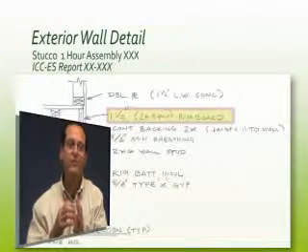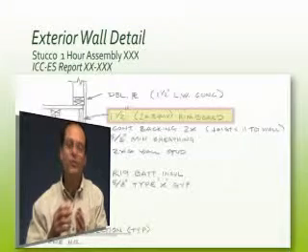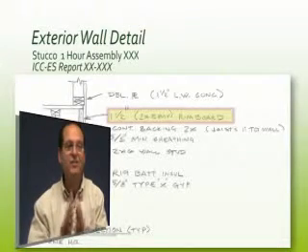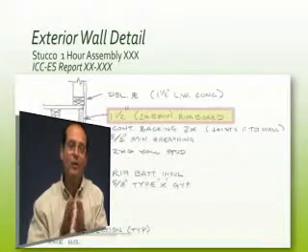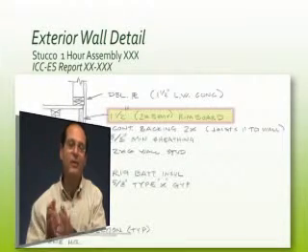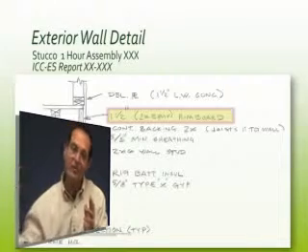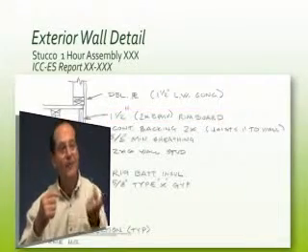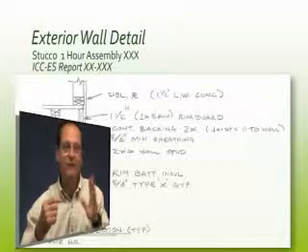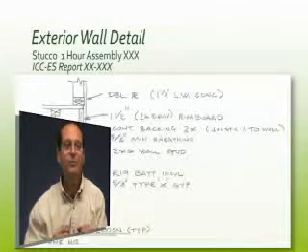So instead of using conventional lumber, we're using just simply an engineered wood piece, 1.5 inches thick, that's equivalent to that 2x lumber that's specified in the code. And this is perfect. This works just great. So that gets its fire from the outside. If anything happens on the inside, again, we're covered with that. So this is a good spec, it looks like.